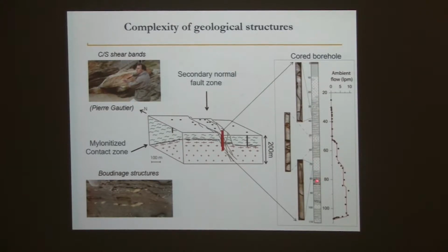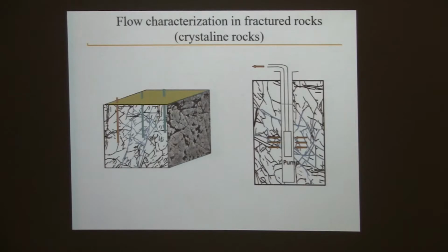Also here, for instance, we see a fault gouge that was very well described from the core, but we don't see very well the corresponding permeability around it. And in fact, the permeability we found, at least at the small scale, is typically linked to some fractures that seem more or less erratic. So we know that in this environment we would have a greater probability to find some permeability around the major structure, but after that, linking deformation and permeability is really difficult. So that's one of the difficulties.